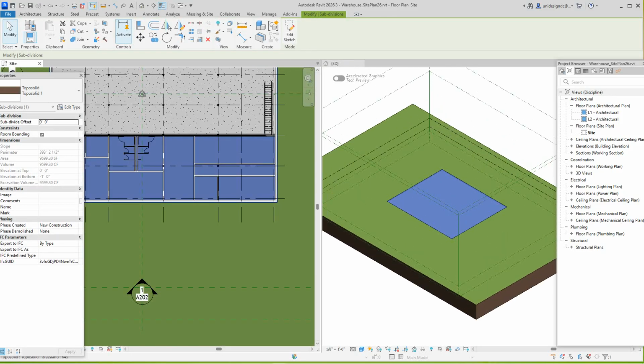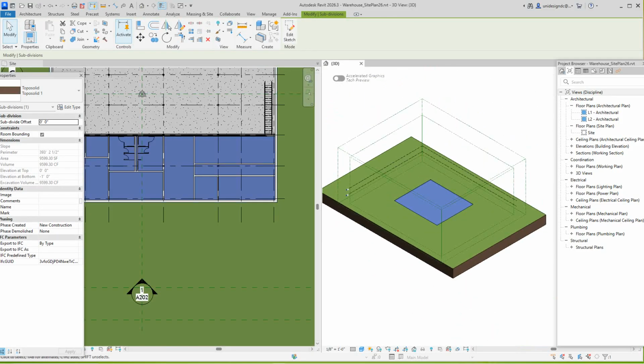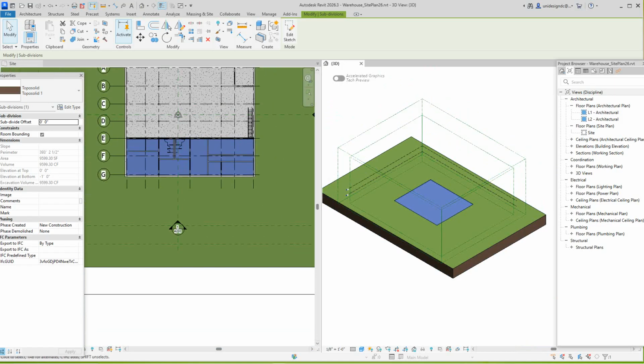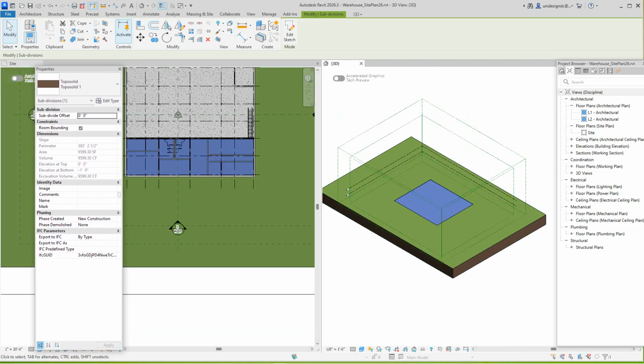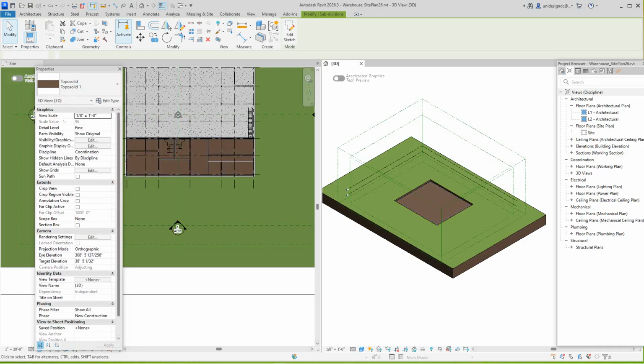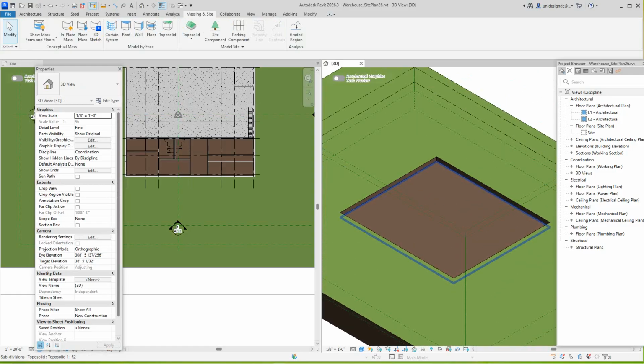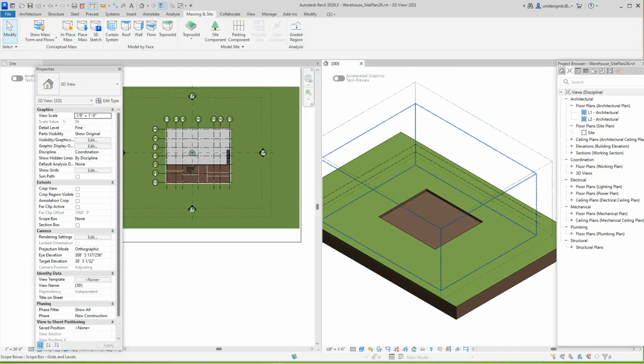So there's our shape. Now we want to drop that down below the frost line, and we're in the Midwest, so we've got to get down 42 inches. So I'm going to drop this down to minus 3 foot 6 inches. Apply. So there's our base, or our subfloor.